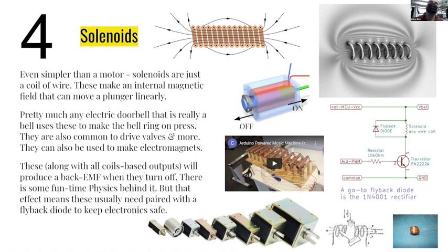It's got this little plunger. I've got this diagram right here that's moving a little bit. It's got a plunger with a spring. When it's not powered, the spring pushes this plunger over here. That's how I know that's the direction it is when it's off. And when you power this coil through the blue and the red line, it's an electromagnet that pulls this perhaps magnetized piece of blue metal in, and this green actuator comes through and maybe pushes a button on that side. It sounds like a weird thing, but here's a lovely application of them.